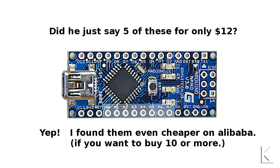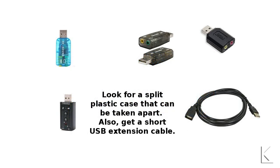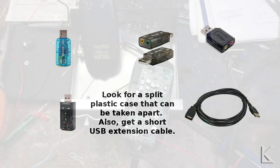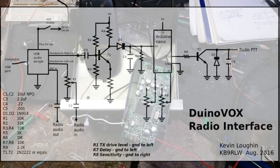Now what about the USB audio? Well, we're not going to build a USB sound card. That would be beyond the scope of this video. However, cheap USB sound dongles are widely available. Search Amazon.com for USB sound adapter, and you'll find many from a few bucks to around $10. Make sure you look for one that has a split plastic case so you can easily take it apart. You'll also need to solder a couple of wires in there to tap the 5-volt USB power and ground.